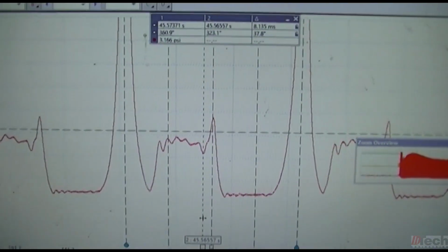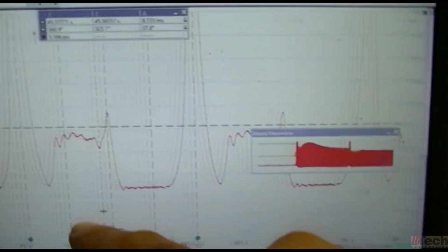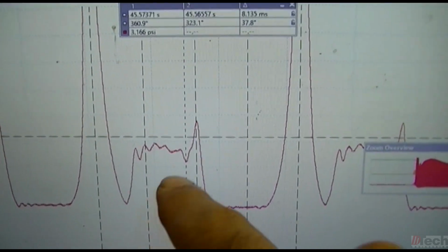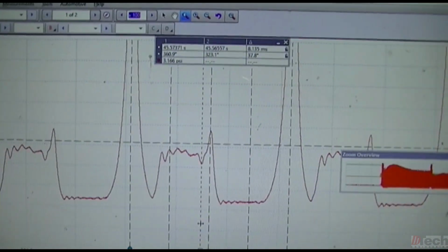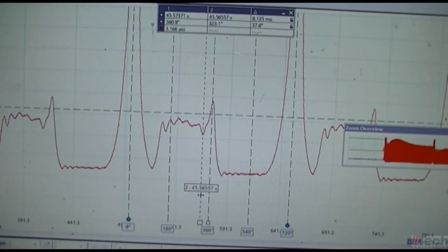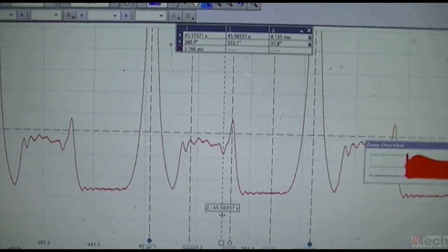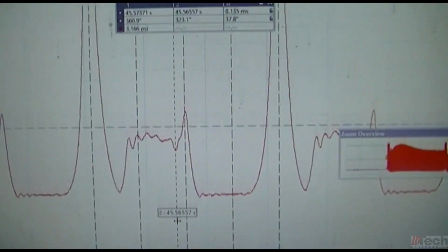In that same stabilized area for cylinder 1, bank 1, at that same point in time, it's showing us 37. So about a 10-degree difference bank to bank with phasing at a warmed up stable point.